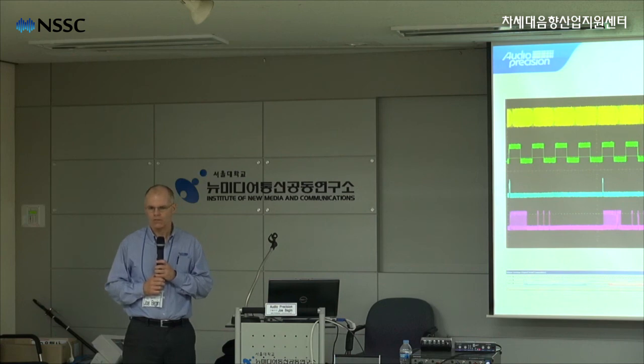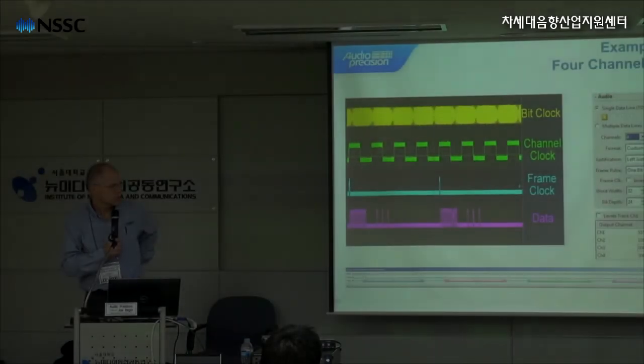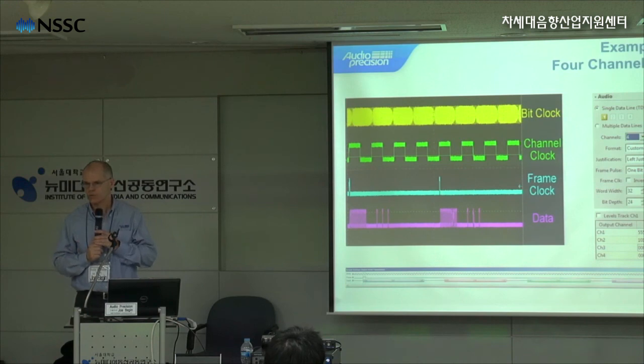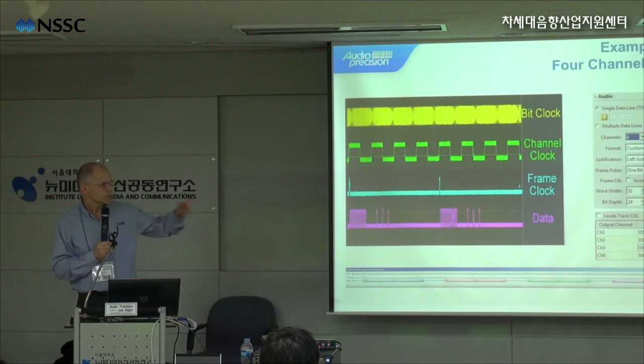And they don't have very high signal-to-noise ratio. Like the residual distortion is typically, the best you can get is about 70 dB. Yeah, I've done some work with them. I haven't measured SNR, but the residual THD plus N would be close, because you're measuring how clean a sine wave you can generate, right? And the best that I've been able to get with those 2 codecs is about 70 dB.